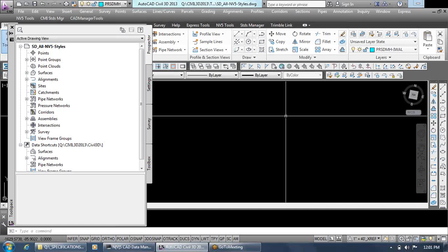Similarly, there's two other things that you guys should be aware of. Try to clean up your files in your folders. Let's say you rename your drawing files. Be sure to then go back and delete your backup files that are no longer associated with that file. Because if I go to some of these project folders, we'll see 100 backup files, but there's only 20 drawing files. So just be sure to do that. That's really important when we go to archive files and just keeping our data really compact and compressed.